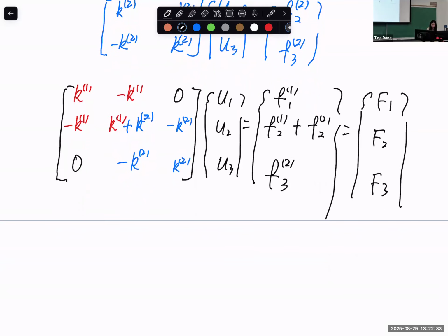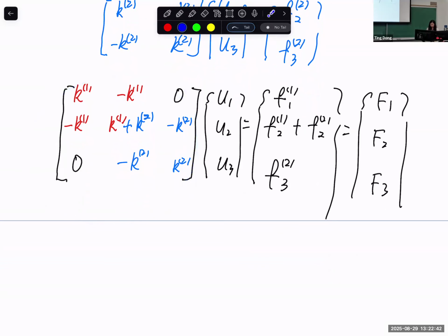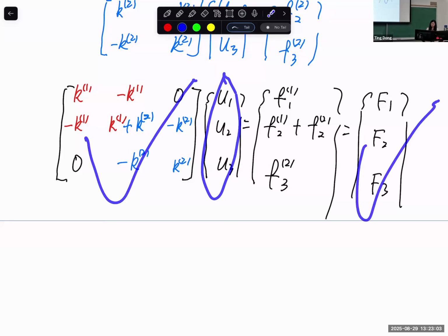So if you check this equation, for structure analysis, you normally know what kind of structure you have based on the material property and the cross section. So you know the K matrix. For our structure analysis, you also know what kind of load it needs to carry. So the force vector of the external applied force is normally given. So we can calculate the displacement response. Make sense? This is a given matrix, this is a given vector. We can calculate the displacement response.